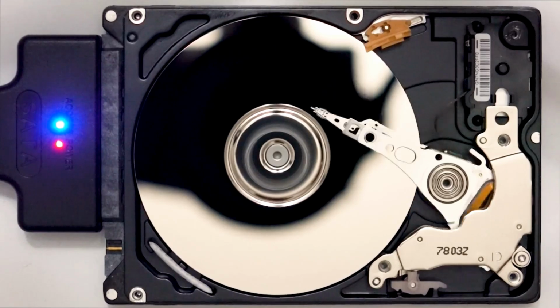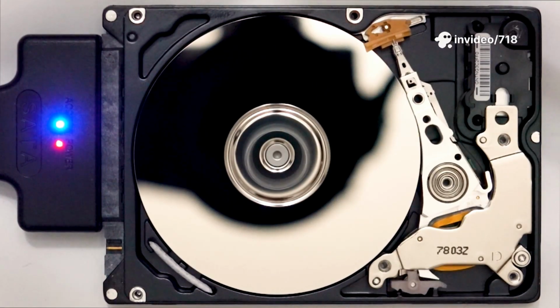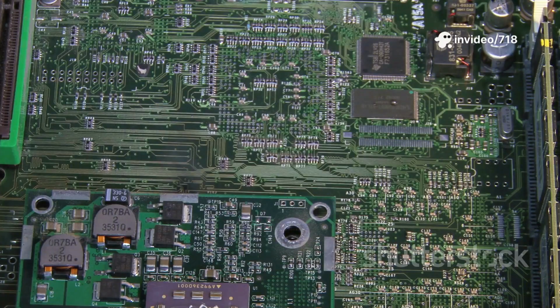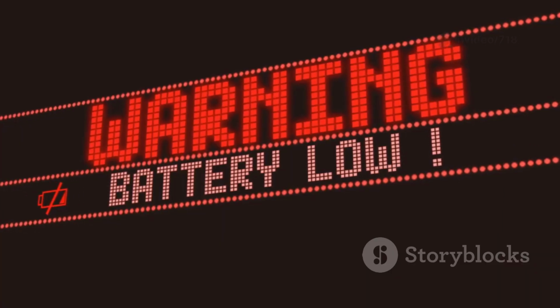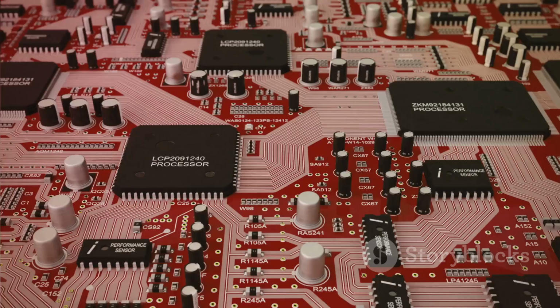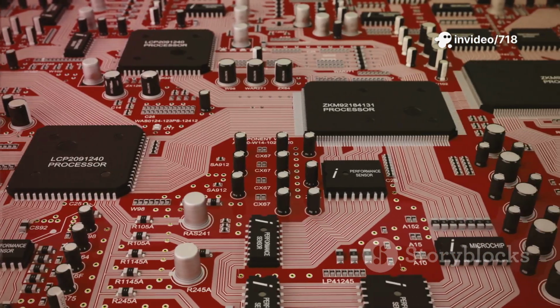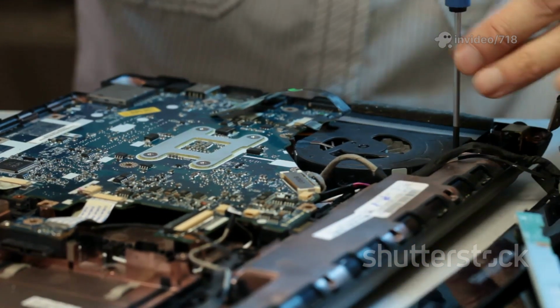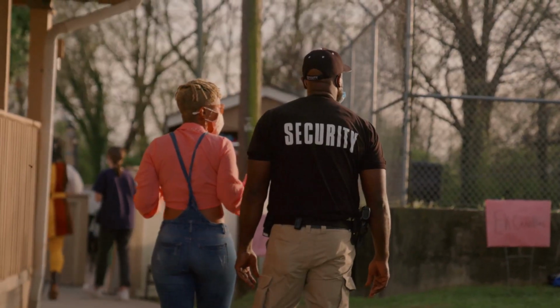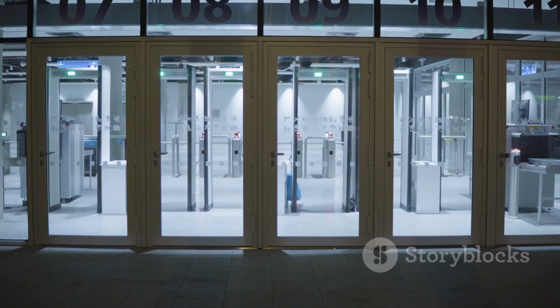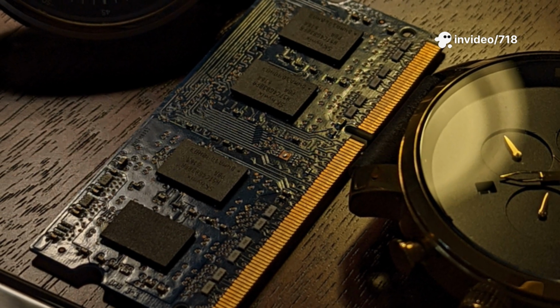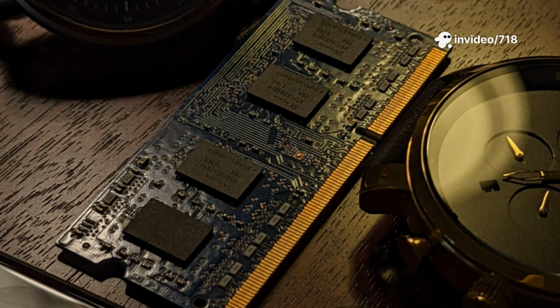The destructive read process takes care of refreshing data that is actively being used. But what about all the other data just sitting dormant in other rows? Remember our leaky capacitors? If a row isn't accessed for a long period of time, the charge will eventually leak away and the data will be lost. To prevent this, the memory controller has a mandatory, non-negotiable duty. It must periodically refresh every single row on the chip. This is like a security guard doing rounds, checking every single door in a building to make sure it's still locked. Typically, according to industry standards like JEDEC, every row in a DRAM chip must be refreshed every 64 milliseconds.